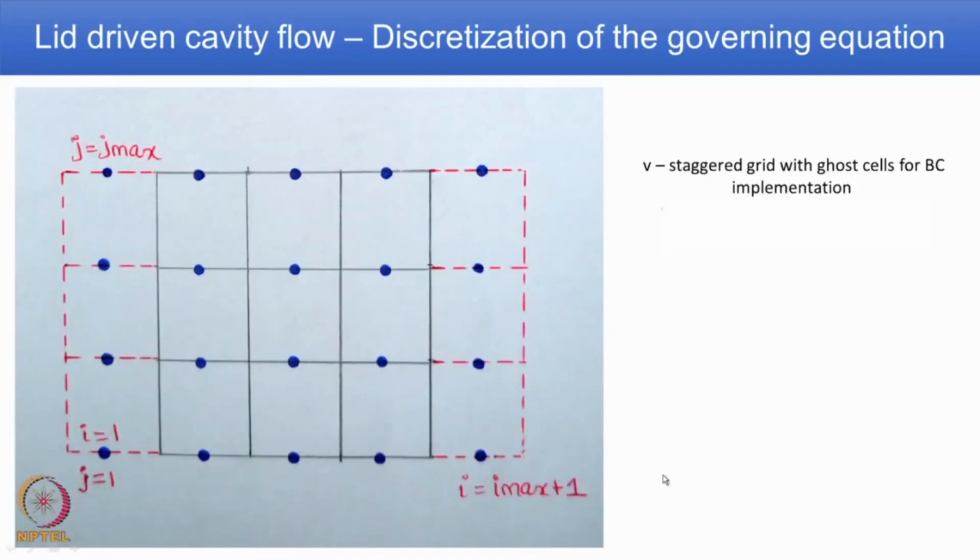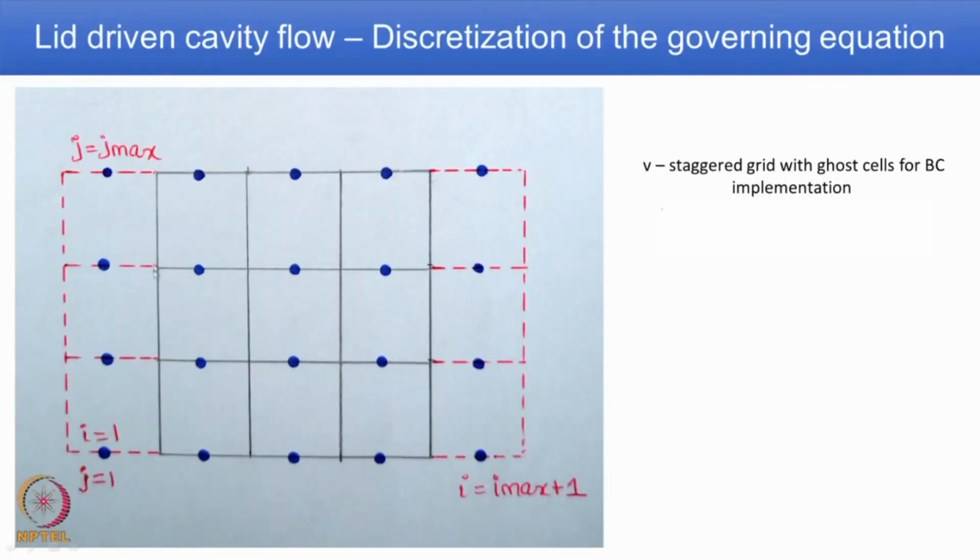We mentioned that in order to have boundary conditions enforced, we should have ghost cells, that is, they are not actually part of the grid that you have defined, but they are extra nodes in a particular direction, and for simplicity we take those extra grid lines at the same distance as the original grid lines. For example, we define 4 by 4 grid lines. So, we have 4 in the vertical direction, so 1, 2, 3, 4. Similarly, 4 in the horizontal, so 1, 2, 3, 4.